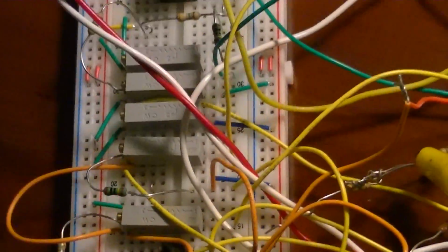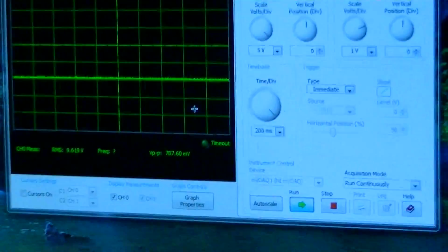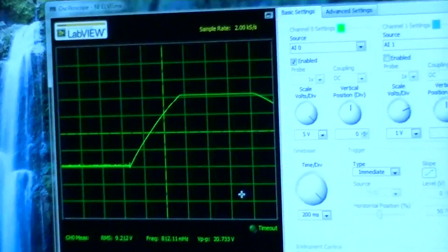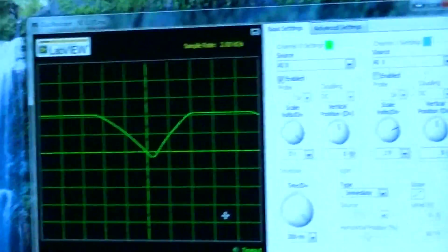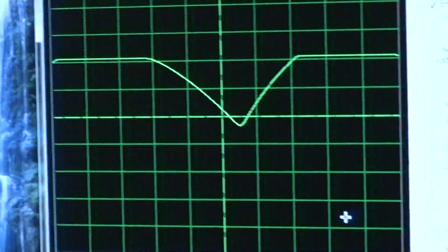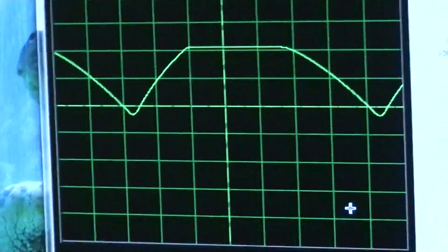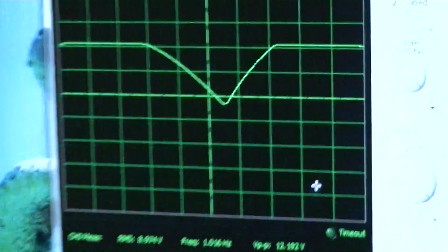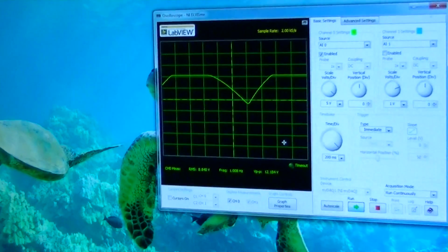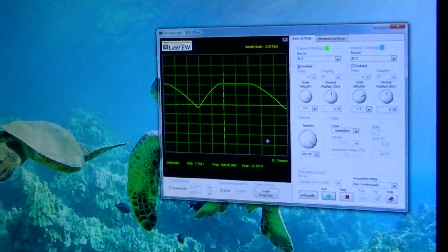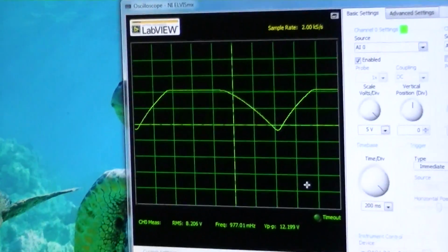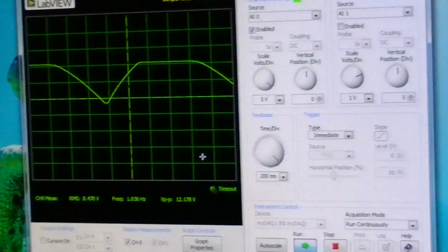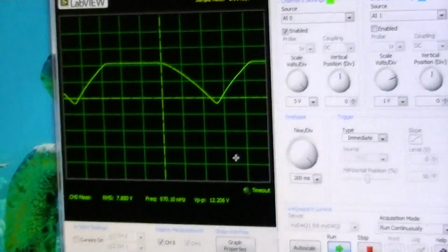Okay, so now let's see what this will do. So now it's not losing any energy. Alright, 1, 2, 3. So you can see, I mean, it's being clipped at the top. That's one of the limitations of analog computing. You see right there on the top of the waveform? It can't represent a quantity larger than a certain magnitude, and consequently it clips the top of the waveform. That would be a perfect parabola otherwise. But you can see that the system is indeed modeling.